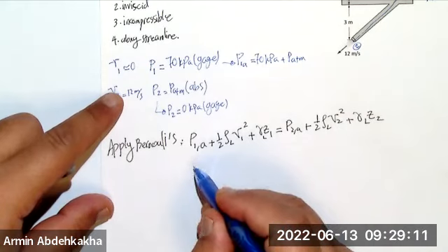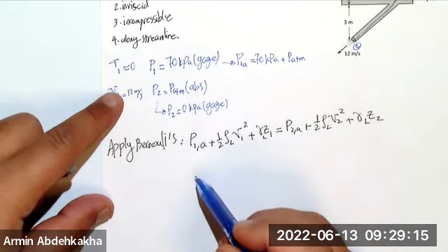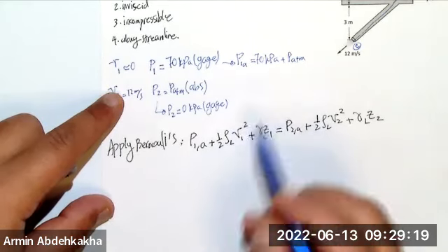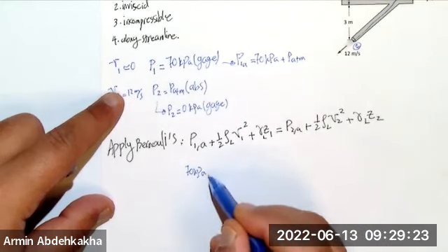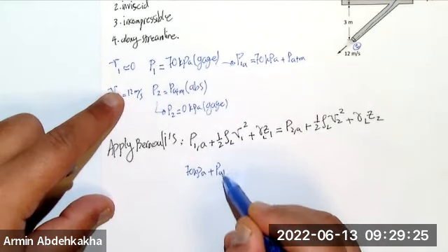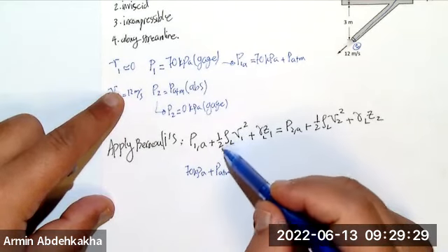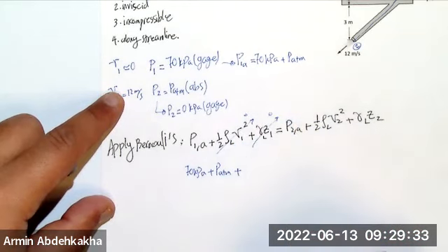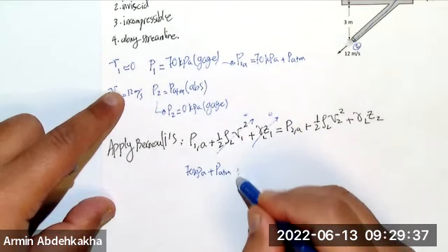Okay, and using those, can I replace that P1 absolute is 70 kilopascal as written here. So 70 kilopascal plus P atmosphere. What is V1? V1 is 0. And Z1, I put the reference there. These two are 0. What else do I have on the other side?